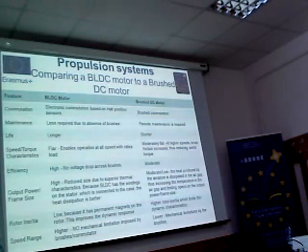This change of supply from one to the other is commutation. So for the BLDC, the electronic commutation is based on the Hall position sensor. Based on the position of the shaft, it will change to supply the coil. However, in the brushed DC motor, it will commutate based on the brushes.